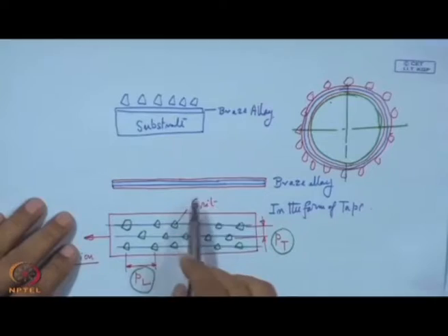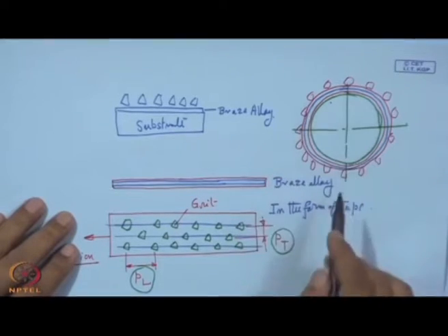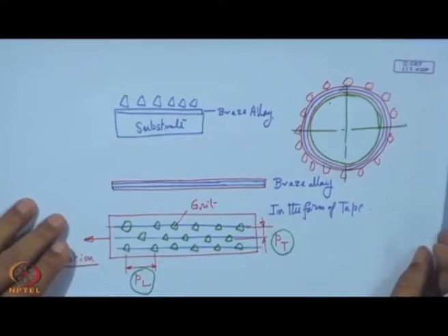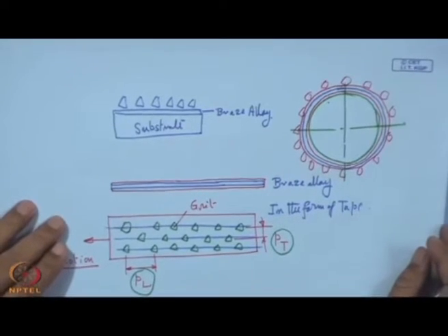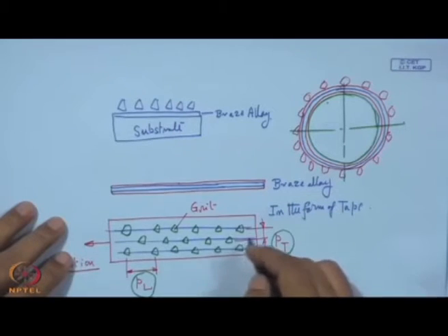What is important is that this tape, which comes in the form of a plastic bond, should be useful for fixing the grits, and by wetting, brazing can be done effectively. This is going to be one of the most effective technologies, using the wetting property of the brazing alloy to fix those grits easily and conveniently, so we need not have a randomly distributed pattern.